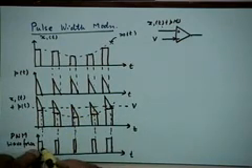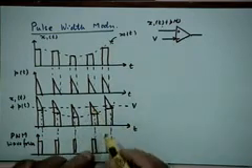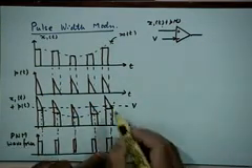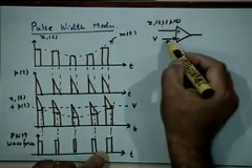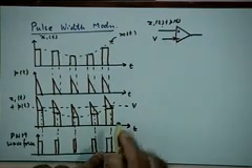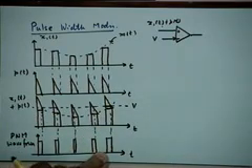So you will get a large pulse width here, a smaller one here, and a still smaller one here. The pulse width will increase here again and increase further here, because during this time this voltage is greater than the reference voltage. So you will get a pulse of constant amplitude, but whose duration will depend on the duration for which this remains above this threshold voltage.